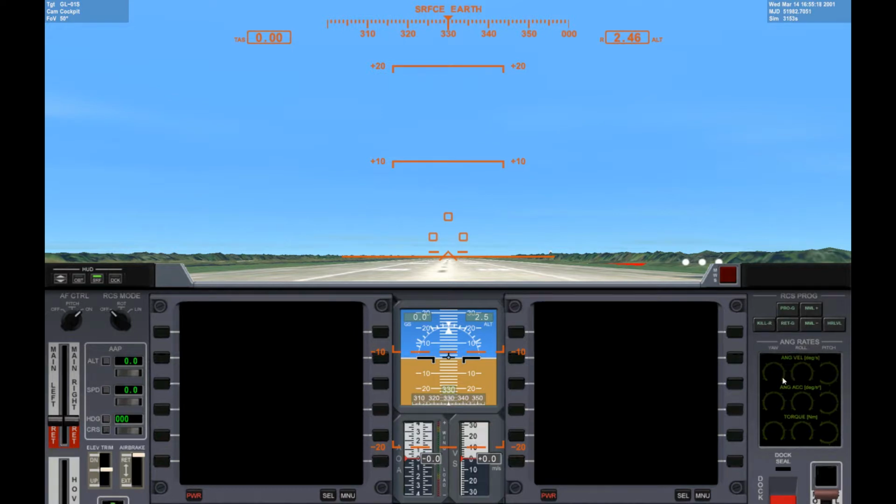Here are your angular rates. So basically, if you've got rates, which will be shown green, yellow, or red on these ticker tapes, positive or negative. This is angular velocity for roll, pitch, and yaw in degrees per second, angular acceleration. And the acceleration will be caused by atmosphere or the air flight control surfaces or the RCS jets while they're firing. And the torque, the amount of twisting force on the aircraft. So yeah, kill rotation will basically stop them all.